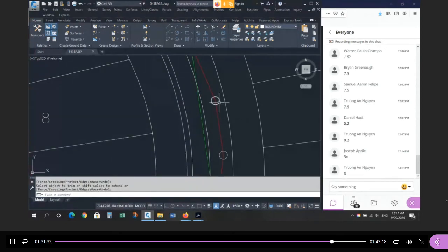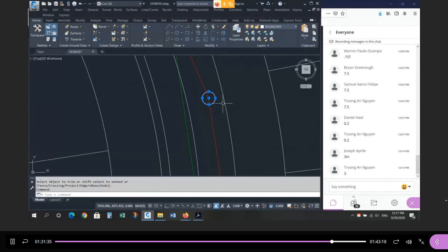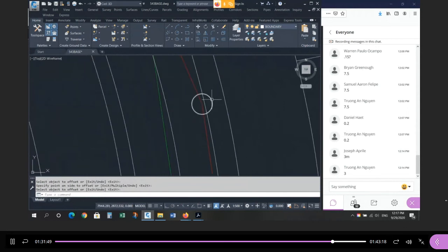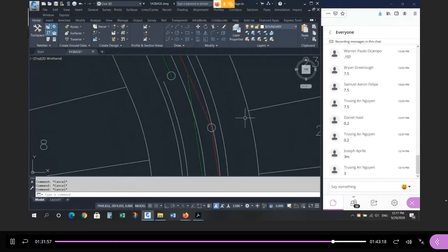When you move the pipes to the outside, now you run into a problem of the maintenance hole being too close to the edge of asphalt. Okay? So if there's a no-touch zone here for the pipe of 1 meter on the outside, there's a no-touch zone of 1.5 meters to the center line of the structure. So 1.5 meters, that's still good. The center of the circle has to be outside this 1.5 meter zone. And that helps keep the two pipes under the asphalt away from the gutter. Because if you ever have to dig down to these sewers, maybe we can salvage the concrete for the curb and gutter. If you put it underneath the curb and gutter, then to dig down, you're going to lose the curb and gutter. So you try and keep it as close to the center of the road.